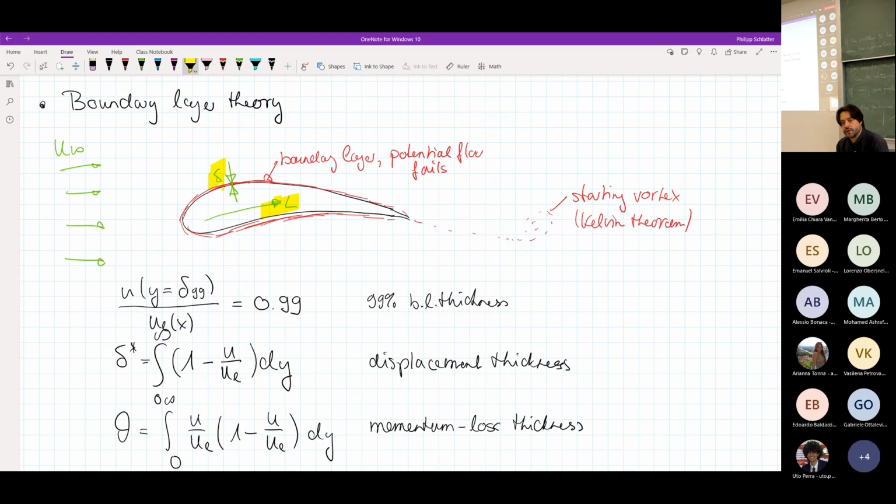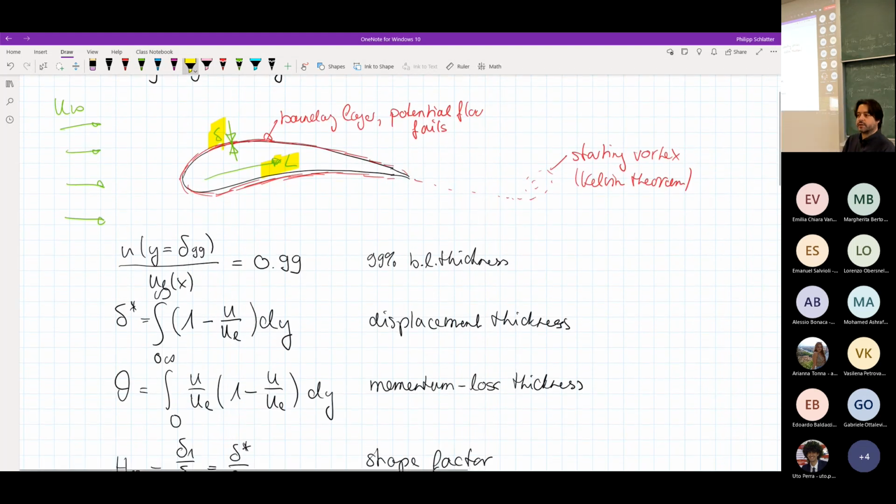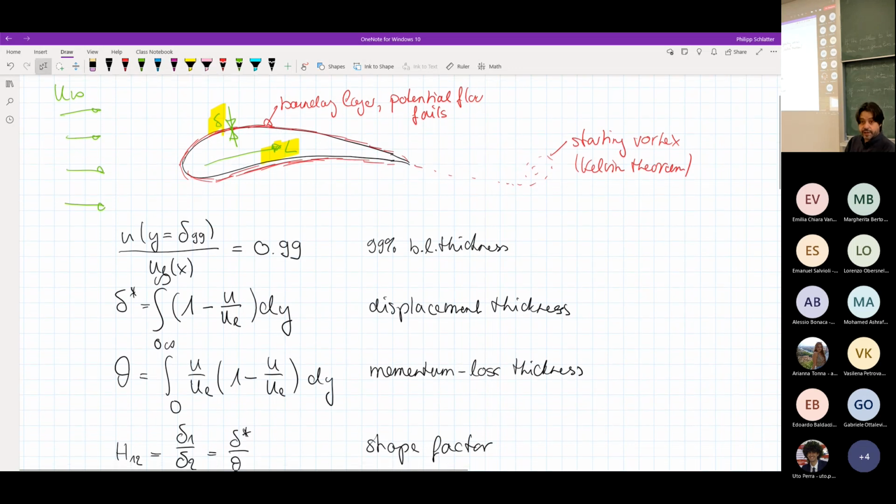That's really the approximation that you use, which you then put in the Navier-Stokes equations, and then you can derive the boundary layer equations, so the Prandtl approximation here. In this way, you actually change the type of the equations from hyperbolic to a parabolic problem, which then is much easier to solve, because you can actually do marching algorithms.